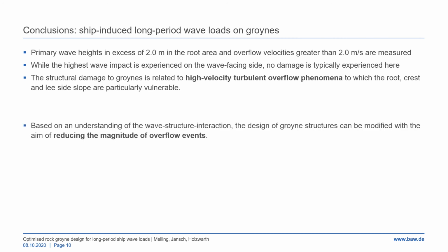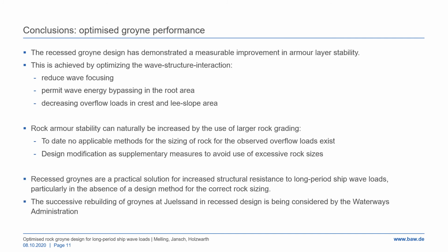With the understanding of this particular wave structure interaction, we now have the knowledge to design groyne structures with the aim of reducing the magnitude of these overflow events, as this is the key to increasing the structure lifetime. The recessed groyne design has demonstrated a measurable improvement in armour layer stability. This is achieved by optimizing the wave structure interaction in a way that reduces wave focusing in the root area, permits the wave energy bypassing, thus decreasing overflow loads in the crest and lee slope areas of the groyne.